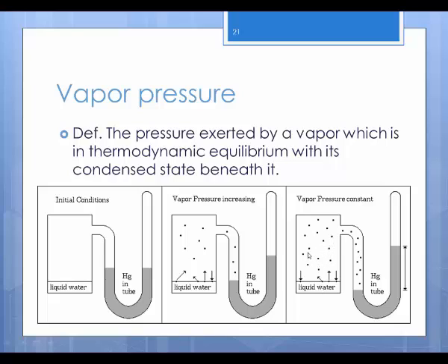So there's some vapor up here at a constant pressure, some liquid here at a constant mass and volume, and these two are constantly condensing and vaporizing, but it's an equilibrium. It's a dynamic equilibrium. For example, if you open a can of gasoline, you'll smell vapor right away because a relatively high vapor pressure of gas has been established inside that can, and it wants to escape so that you can smell it.